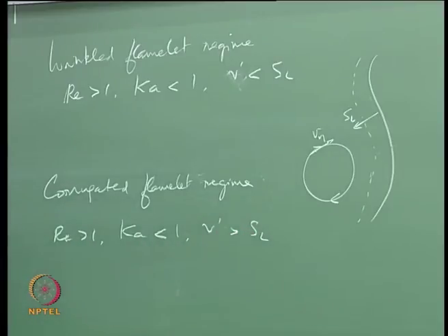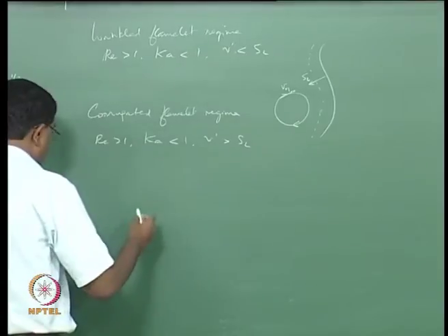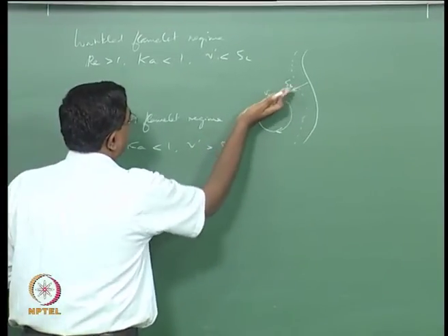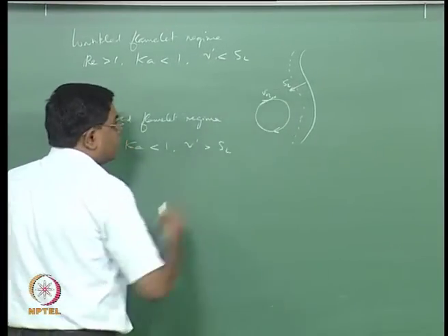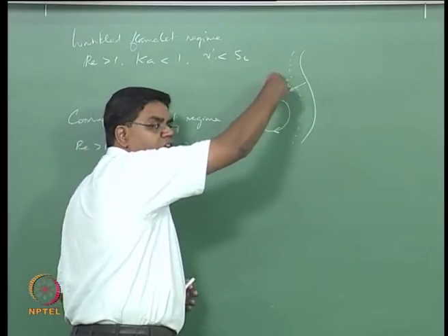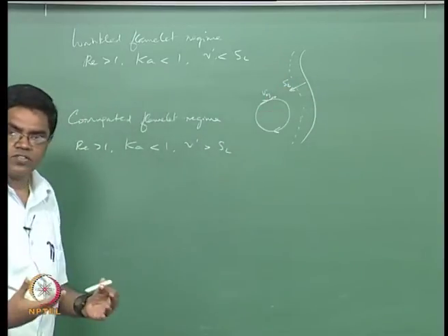This means the intensity is now larger than the flame speed, so the eddies are going to make their presence felt on the flame a lot more. The velocity here is going to be large, and correspondingly the flame has to give way. That's how the flame always tries to do things.